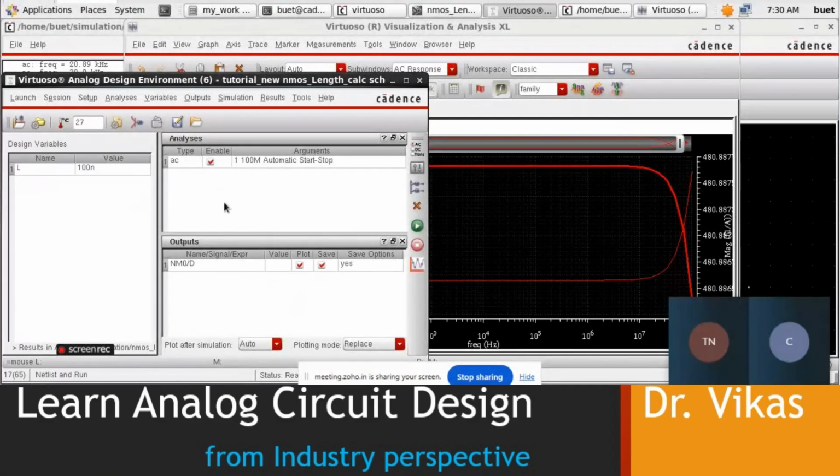Now this kind of experiment, it is not that you will be repeating it forever. See, these are the stepping stone for your next level of experiments. As and when we proceed, after a few sessions, we will not be working on these things. We'll just fix those W and L values directly, and move forward. But these are the design steps that you have to follow. Let's say, for example, you want to design an amplifier, and in the amplifier you want to set up the W and L ratios, and to fix those W and L ratios, this is how you are supposed to do in the initial stage. When you do it in the initial stage and you get the value of L, no need to repeat it forever. So that's how you can do all these kind of things.